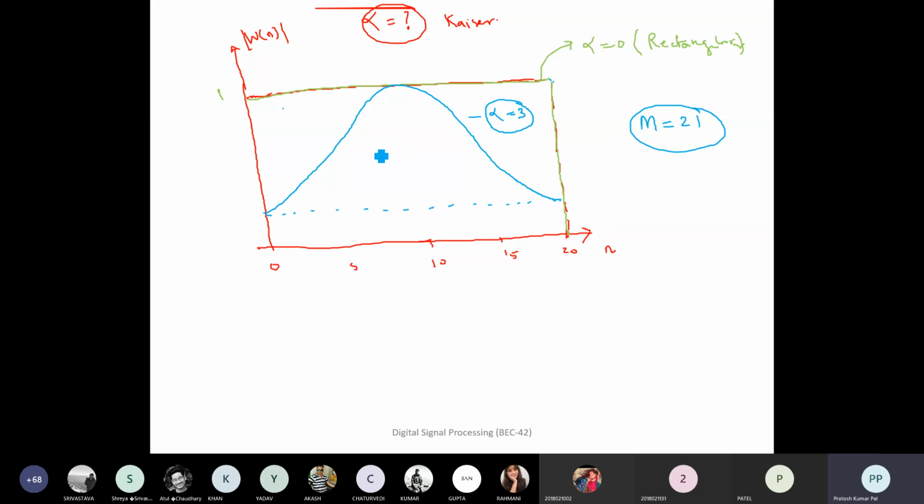So this is your window function that is defined having some starting magnitude. This magnitude could be like 0.08. Instead of starting with 0, it is starting with a magnitude. So this is basically defining a Hamming window.